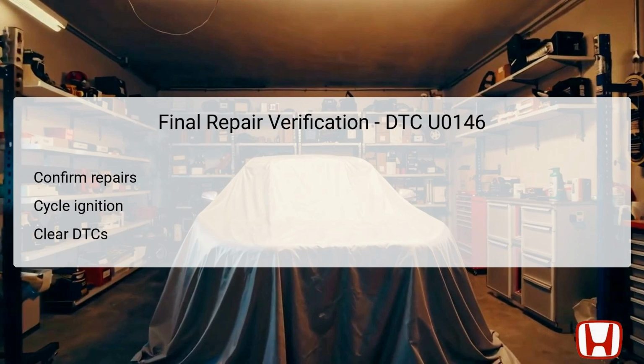Following this, the next step is to clear any DTCs stored within the system, utilizing a diagnostic scan tool to remove all fault codes. Once cleared, taking the vehicle for a test drive can help to determine if the issues persist or if the repairs have been successful. Monitoring the performance during the test drive will confirm the reliability of the system, indicating that the MIL remains off and the shift indicator operates correctly. This verification process ensures the vehicle avoids future DTC occurrences while confirming restoration to optimal performance levels.